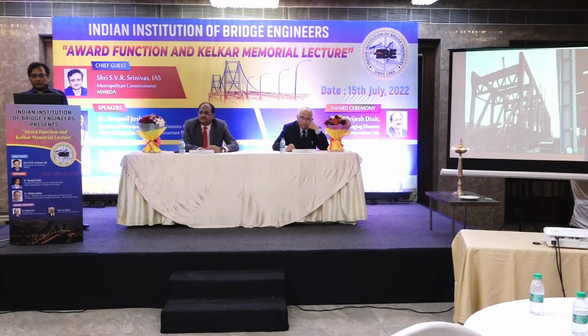This bridge was fabricated in Nagpur only, and it was fully assembled to check the camber and other accuracies. It's a contractor's fabricator workshop. It was fully assembled there, and all parameters were checked. It was then dismantled and moved to the site.